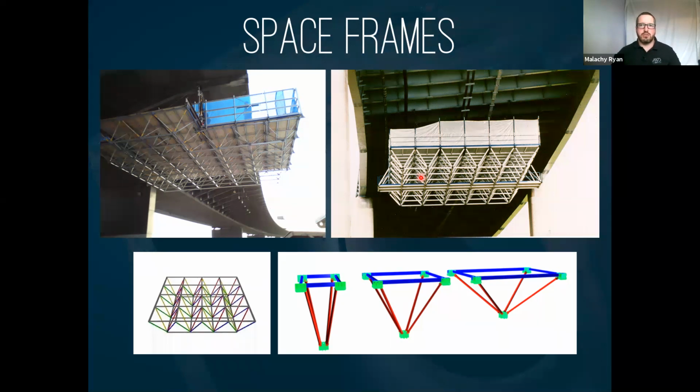They're very strong, they're lightweight in themselves, but also the individual components are lightweight. They can do quite large spans of 25 meters plus, very modular, so they can be built by a non-skilled workforce, and they're very rigid, so when you get wind loads and imposed loads applied to them, you don't really feel that as an operative on the platform. So you typically have a structure that looks like this, the size of a tennis court, typically that kind of scale. You put 4 cables on it, 1 in each corner, and you lift it tight to the underside of the bridge to do your works.